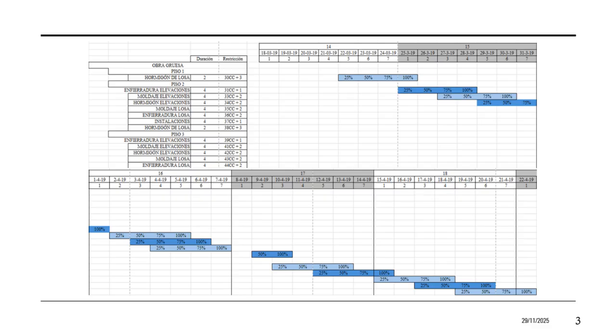Now, here's the planning analysis carried out for the project, applying the Last Planner System approach. The intermediate plan for the 4-week window starting at week 15 is structured around maintaining continuous production by anticipating and resolving constraints before each task enters the weekly plan. In this period, the emphasis is placed on evaluating what conditions must be met for the structure cycle to advance